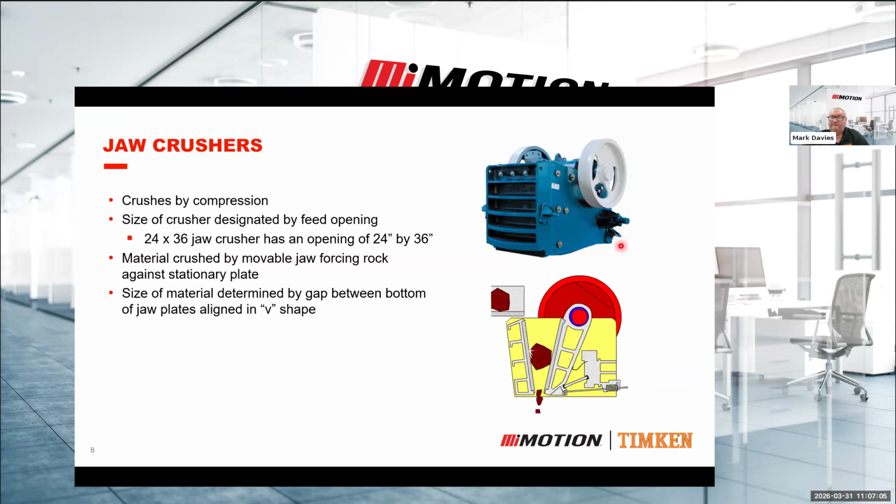Note that you'll always have flywheels. These heavy metal flywheels give the inertia to actually crush the rock. So when a larger rock gets jammed into the crusher, the jaw still has the inertia to continue moving and actually crush and fracture that rock down.